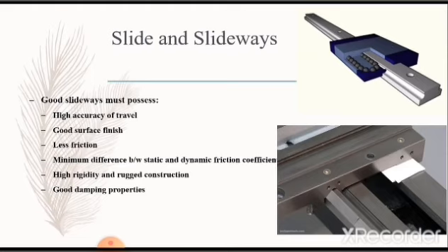High rigidity and rugged construction. Why? Because it has to bear maximum loads and forces, so the withstand capacity should be high. Good damping properties, meaning it can absorb any kind of vibration. So these are the good properties that a slideway must possess.